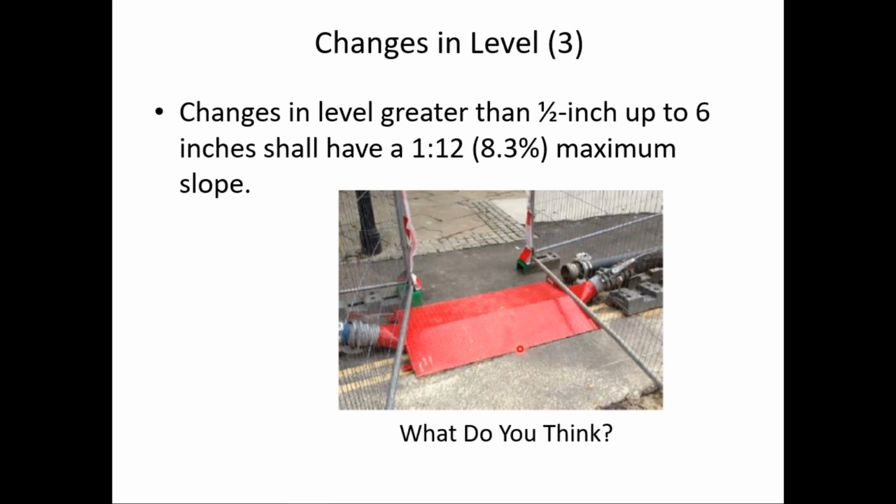I think it would be impossible for someone in a wheelchair or maybe even with a walker to get over that. But also for all pedestrians, able-bodied people might be able to step on that, but notice it looks like it's just normal enamel paint. And I imagine when that surface gets wet, it probably gets pretty slippery. So I have not only accessibility but also safety concerns with this setup as well.